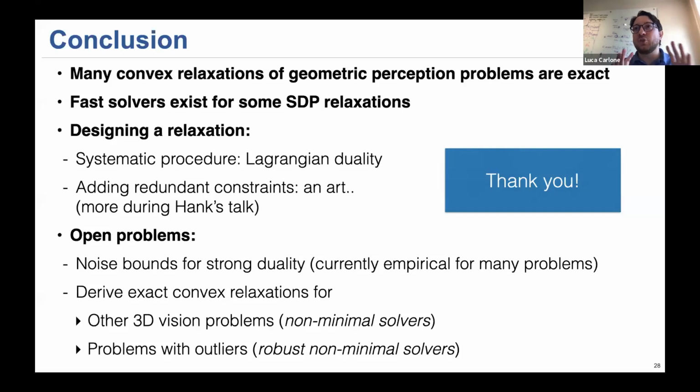Another potential solution is to realize that in SLAM and in pose graph optimization, you don't need to optimize at each time. Actually, if you do not have loop closure, the optimal solution for SLAM is just to concatenate the odometry. So ideally, more than being just batch, this is a solver that you need to invoke only when you have a loop closure. Every now and then you get a loop closure, and in a separate thread you run this, which is still pretty fast, to compute a globally optimal solution.